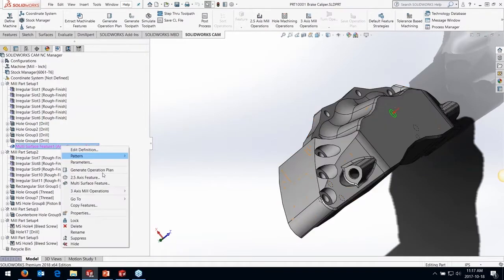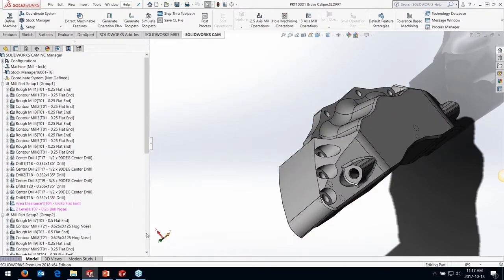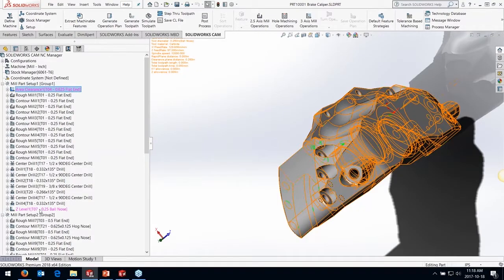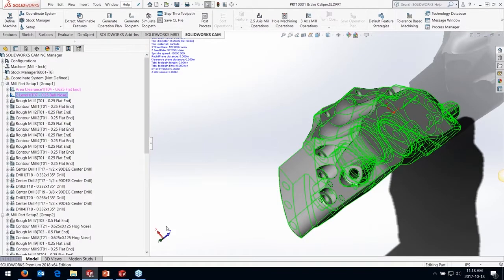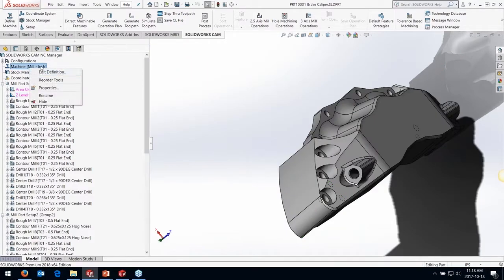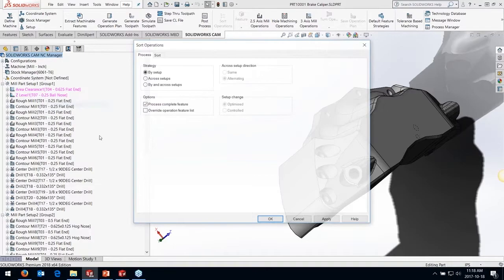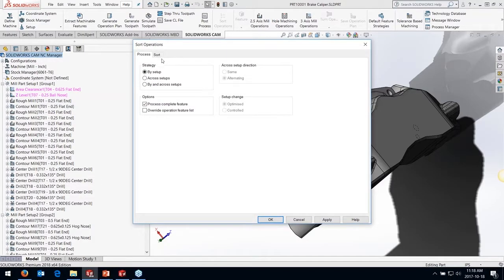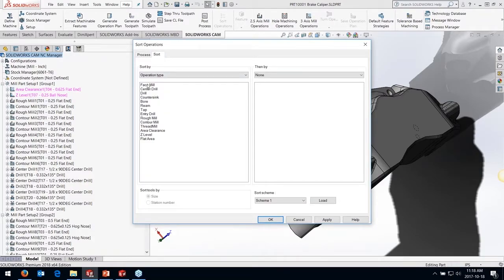Another great thing about it, I can see the holder. I can see, hey, I've not actually roughed this material out yet. Maybe if I want to go in and 3-axis rough this profile first, I can do that. But it will warn me, or it will just give me a cut. I can control if it'll actually pause and say, hey, you're doing something silly, go and stop, tell me what's wrong with it, and then it will give me an idea of what I need to go and fix. Or I can just cut it and just watch my holder plunge straight into my material. So I can simulate that toolpath, see what's going on, verify it, and then go back and fix it.